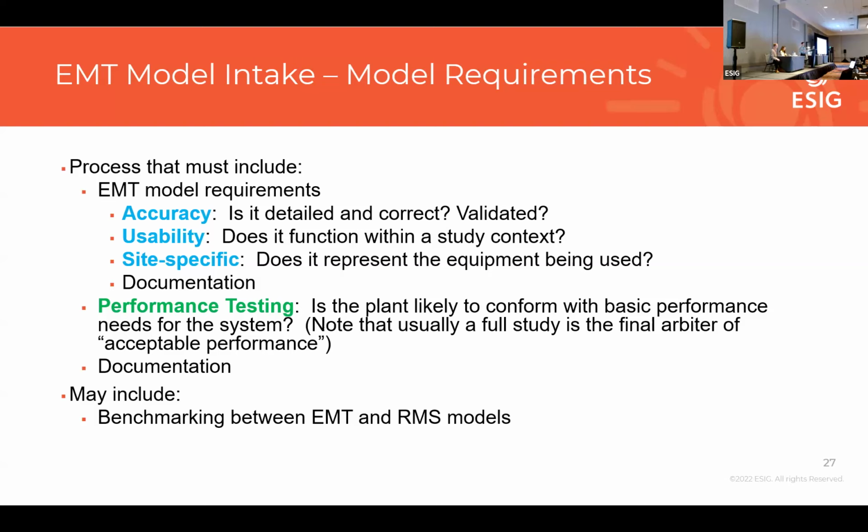And within that accuracy, we have certain very specific accuracy features that we look for, as they pertain to the study we're doing. If we need to look at some very high-frequency phenomena, and we want to make sure the model switching is included, then we would require a switching model, versus other cases where we can have a different type of model that is more approximate at those higher frequencies.